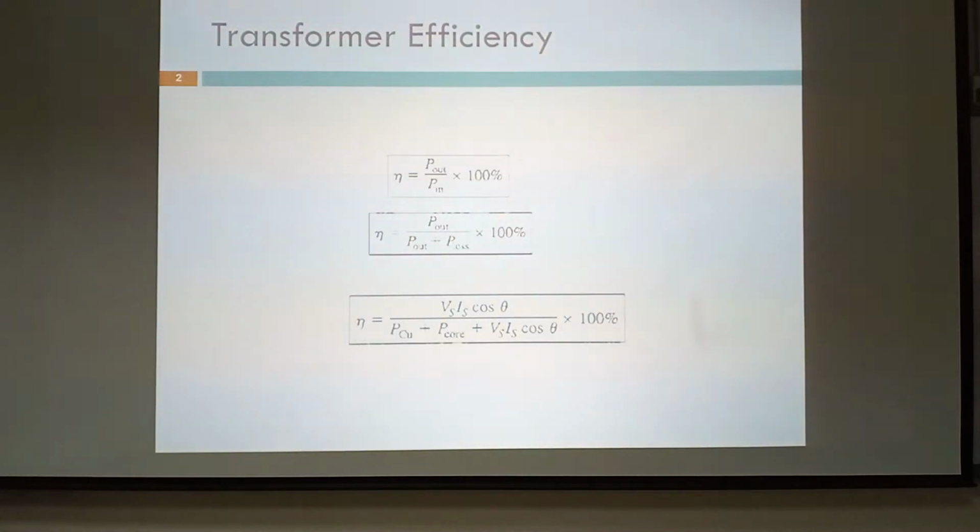So one was the phasor diagram under the lagging power factor. The second was when the power factor was unity, and under the third condition we considered the power factor to be leading. Then we saw the voltage regulation: the voltage regulation will be negative in case of leading power factor, and it will be positive in case of lagging power factor and unity power factor.